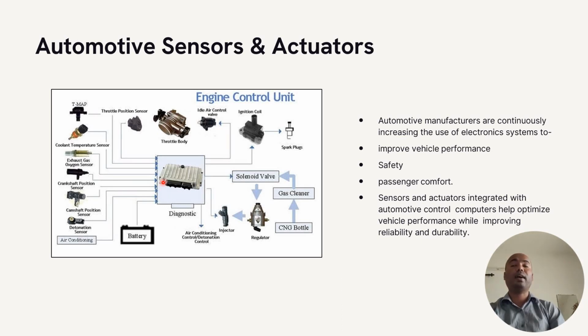All those things are connected with the CAN network. So all the sensors, all the actuators and the ECU are connected with the CAN, controller area network. All the sensors and actuators receive the signals in parallel, so only the respective sensor and actuators will function.